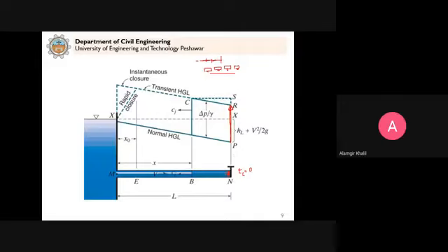So what will happen with this increase in pressure? Because the effect is transferring upstream, this will set up a pressure wave. This pressure wave will travel with speed C. Now we consider the pipe and the liquid both as elastic.